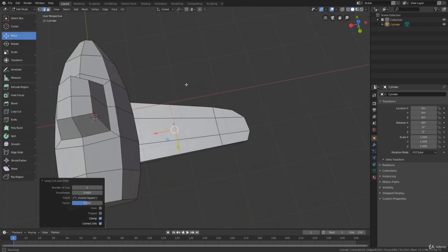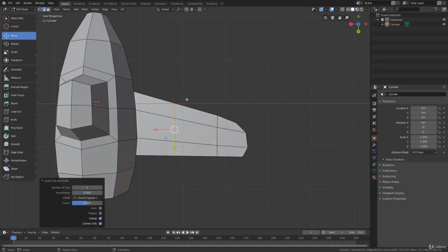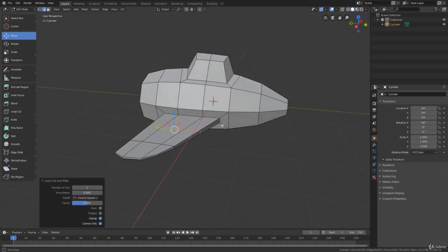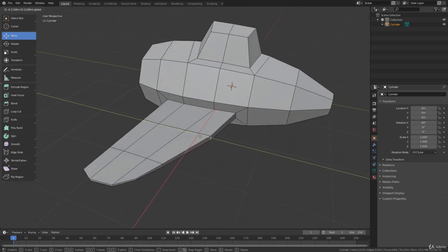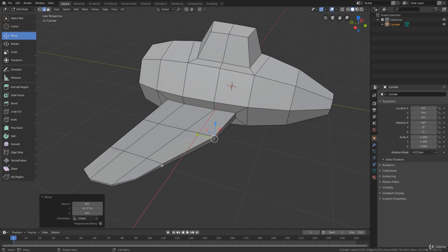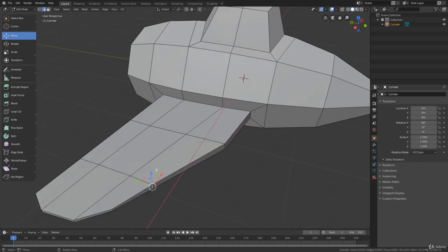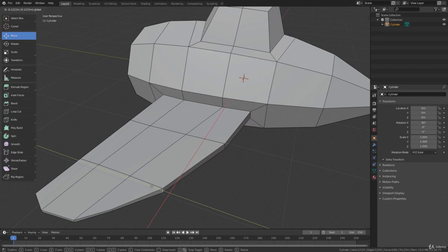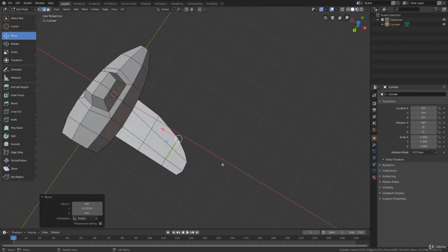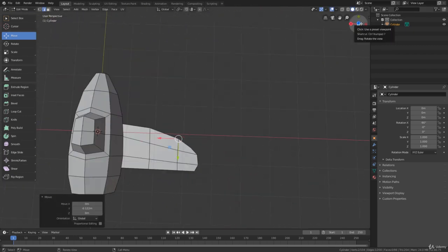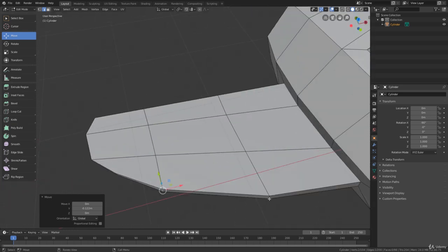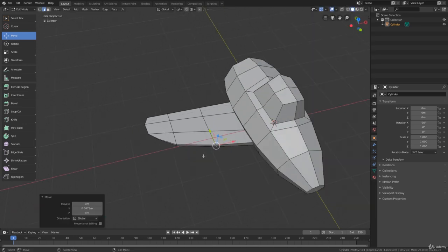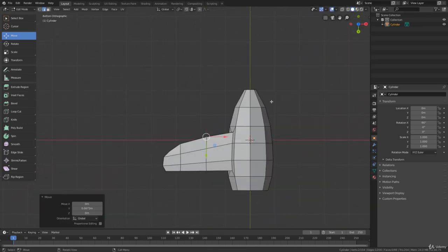and this time it is already straight. So now that I have those segments, I can activate the Move tool, select that edge in the back of the wing and move it back a bit, and the other one that I just created, select only the vertical edge and move it back a bit. The point here is to make that back part of the wing look round, okay? Because those old planes had this back part round like this. This is kind of a Second World War airplane, okay?